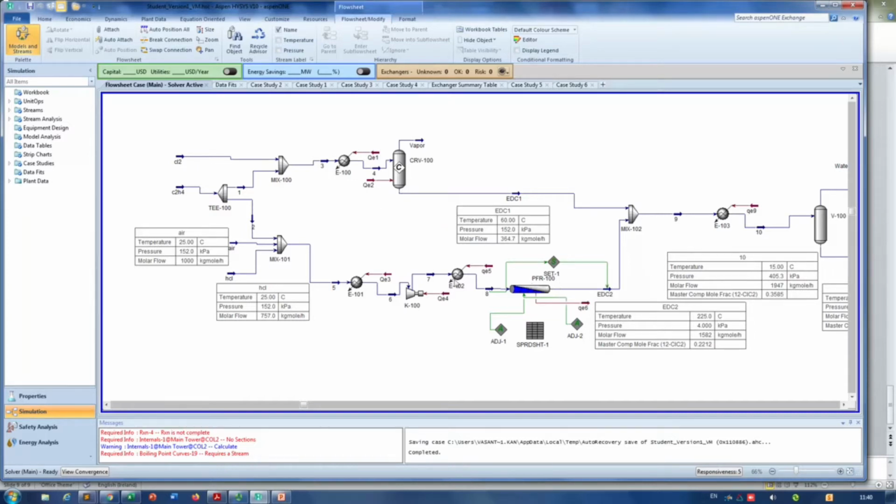And then we are also manufacturing ethylene dichloride from the oxychlorination process. Obviously for that we need hydrochloric acid, oxygen, and ethylene. Obviously we have to maintain some temperature and some pressure. And then I modeled the catalytic reactor as a plug flow reactor, and I also showed you how to adjust the reaction time and so on.